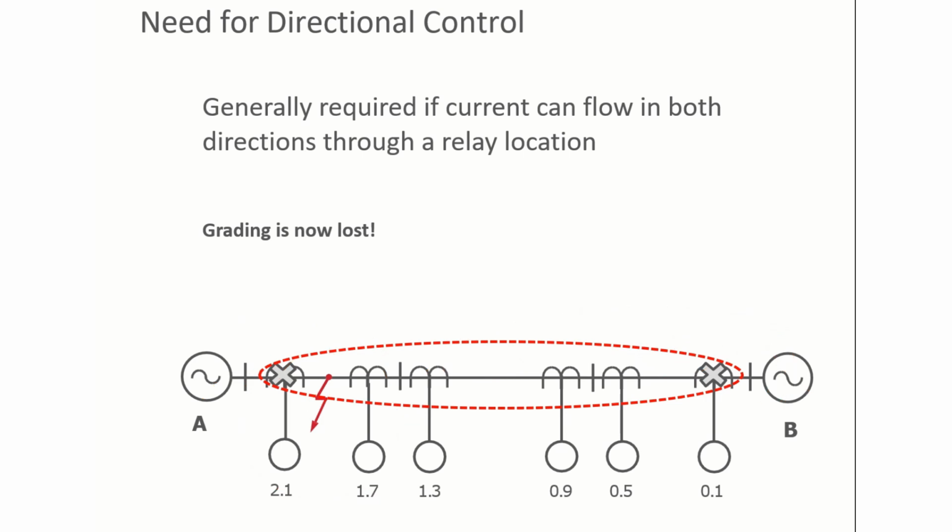In this case, we can use directional overcurrent relays in such a way that these relays operate only on the basis of the direction of current flow. That means these relays should only operate for a given direction of current and should not operate for the second direction. Some people might ask here that the current is going to change every 10 milliseconds for a 50 hertz system.